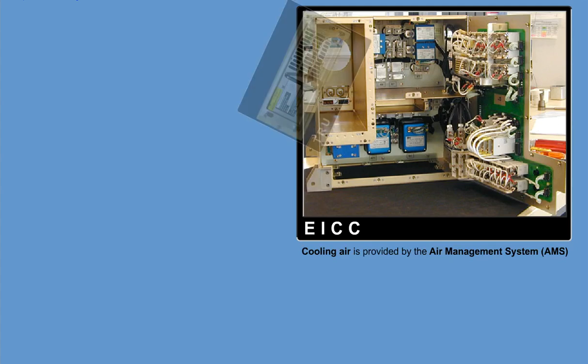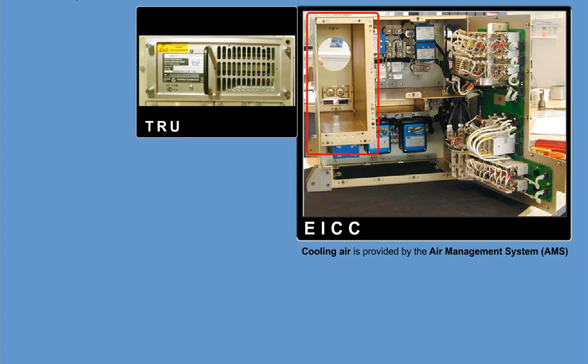The EICCs are mounted and bonded using 4 bolts through the 4 mounting feet. Cooling air is provided by the Air Management System and drawn through the TRU to ensure adequate heat dissipation. All other EICC components are cooled through natural convection.